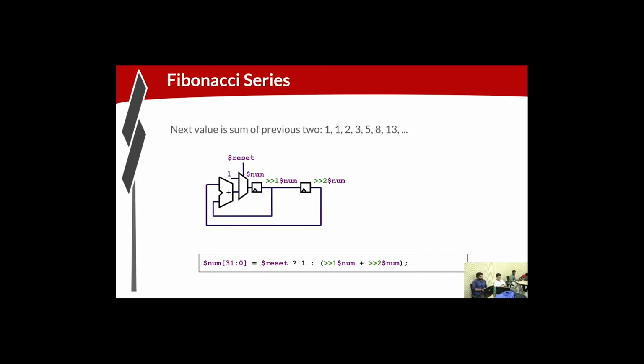Different pipelines, yeah. You can define any number of pipelines in your design. Those pipelines can communicate with each other. Is that the question? We're going to start out just looking at simple examples that are one pipeline. Even the CPU that you design, it's all one pipeline. We don't even have to talk about it for the entirety of the course, but you can split your logic into different pipelines, and those pipelines can consume signals from the other pipelines.